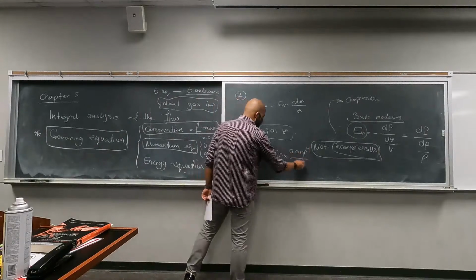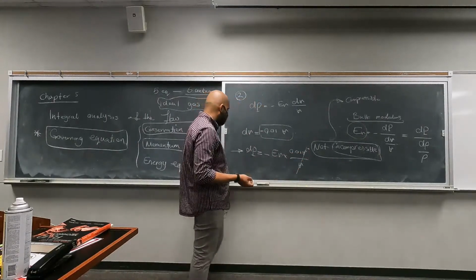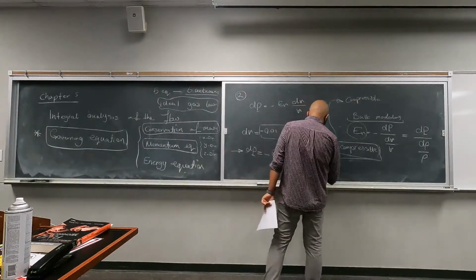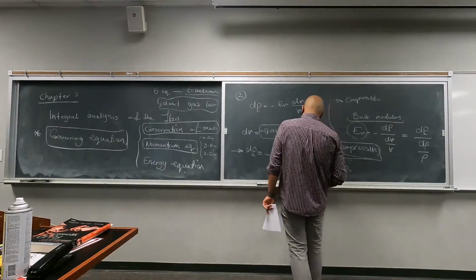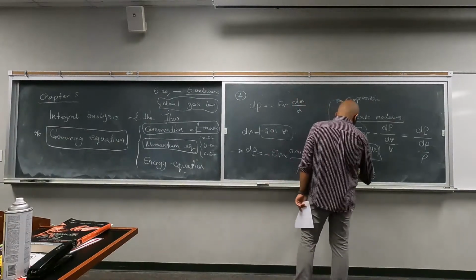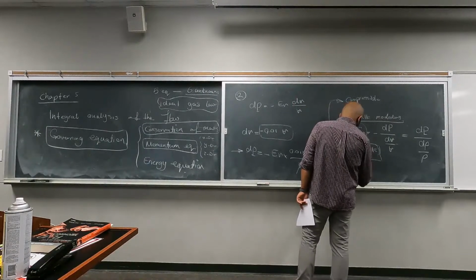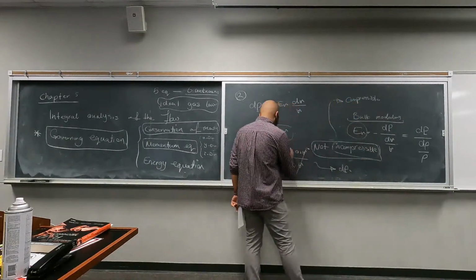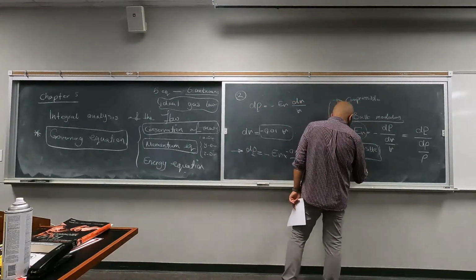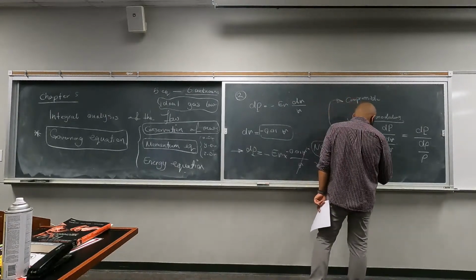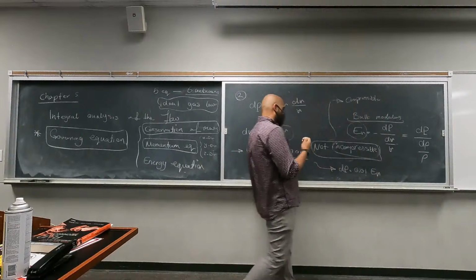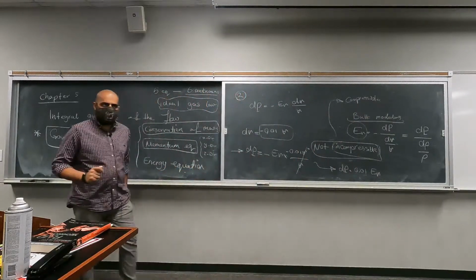These cancel out, so you don't need to know the volume. The only parameter you need to know is E_V, the bulk modulus, which you could have assumed a constant number for. And this is a negative sign actually. So the amount of pressure increase has to be 1% of your bulk modulus. And that is the bulk modulus of seawater.